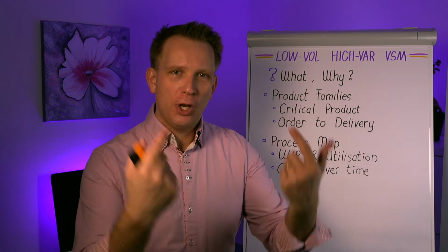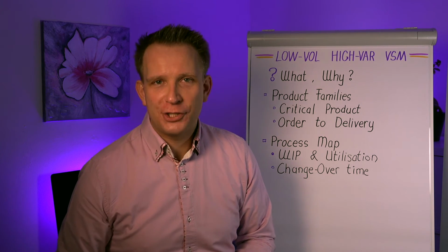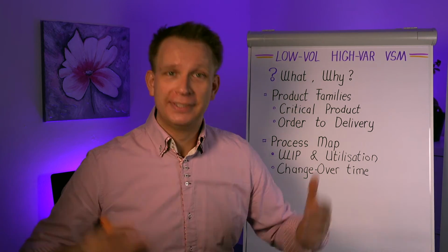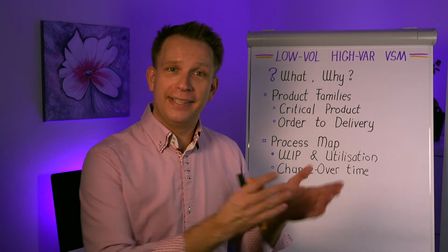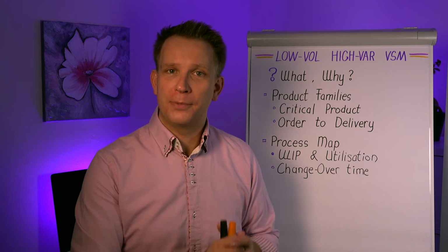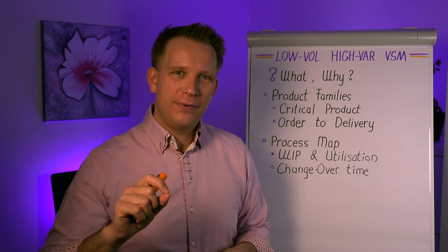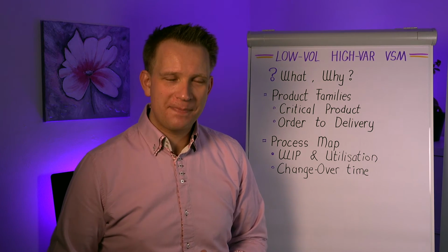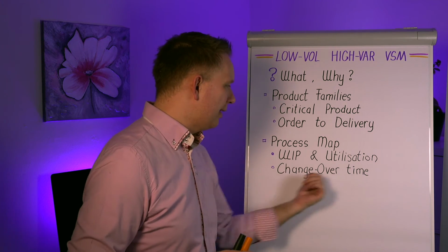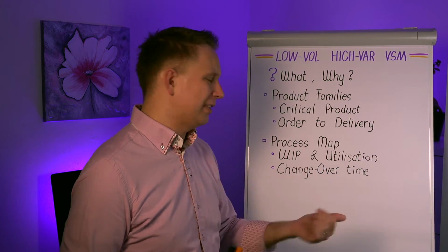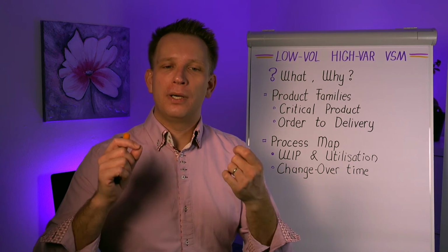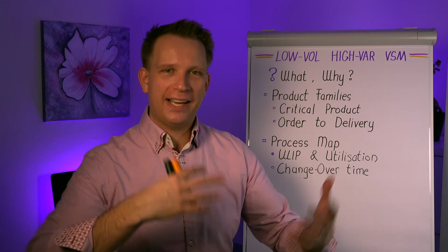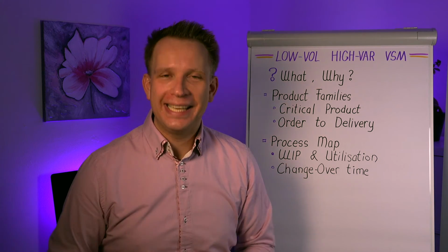Now, when you do a lot of changeovers, first reaction might be, well, that means that if you shave off 10 minutes times 20 times a week, that is a lot more than even an hour shaven off 3 times a week. But the main thing is, when you have this high variation demand on your factory, then having large changeovers, so long time, high difficulty, it will completely stifle your planning. You will not be able to react flexibly, which is needed in these type of factories.